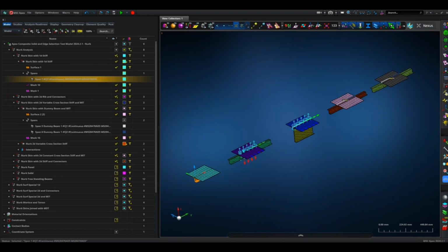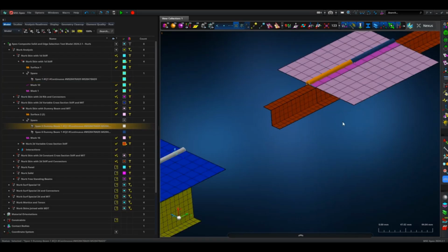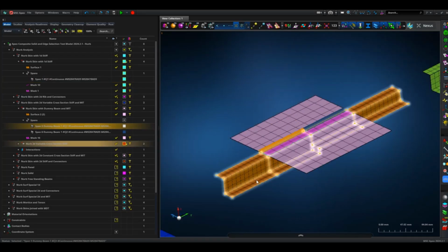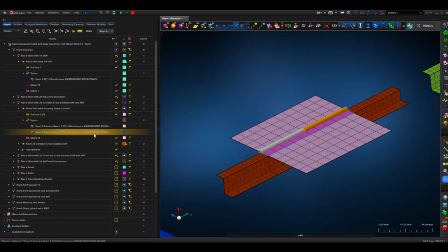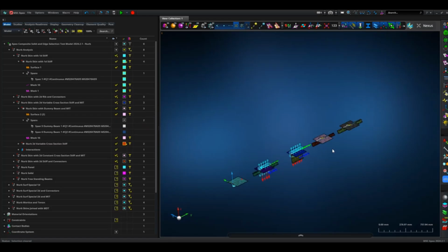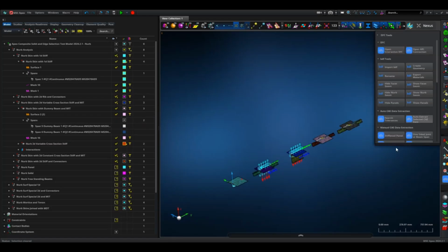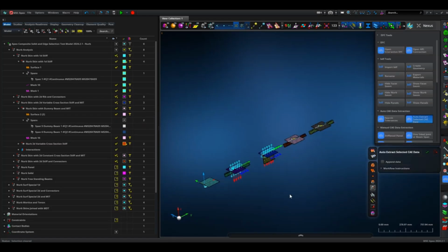We use beam spans to identify different panels. There we've got our 2D beam span, and that one we specifically want to use to calculate data, because that stiffness is actually changing in section across the beam span. So we assign 2 beam spans here to accommodate that.